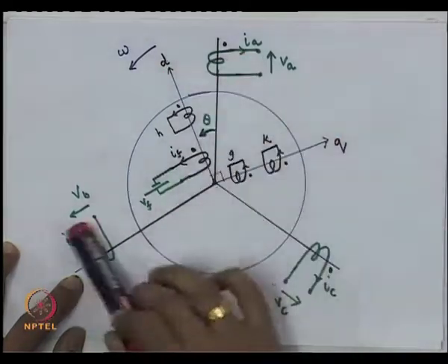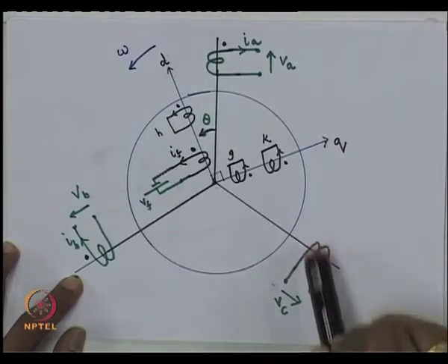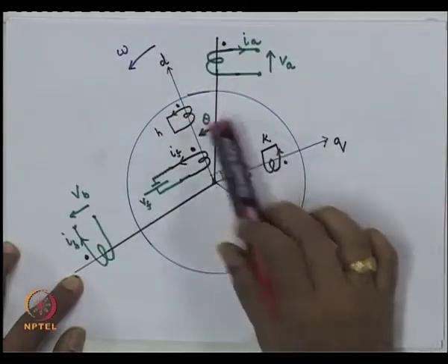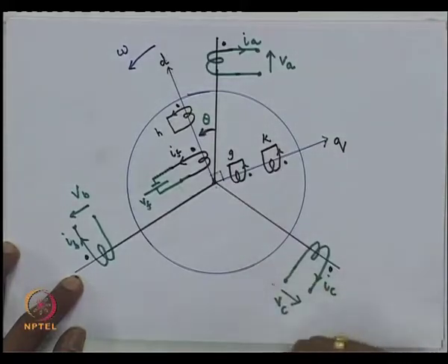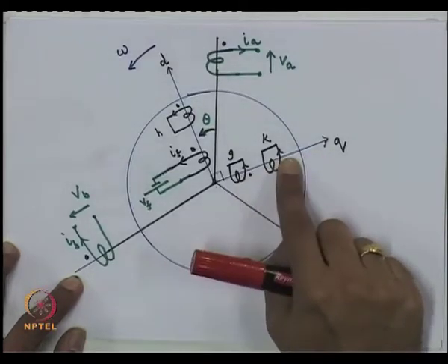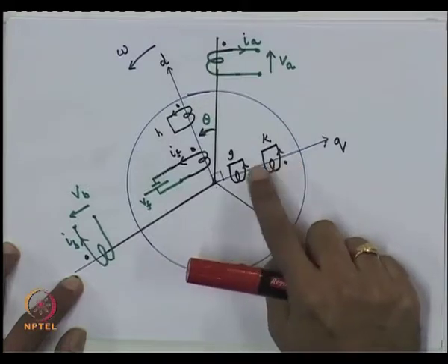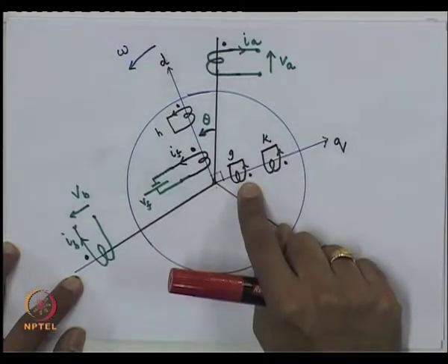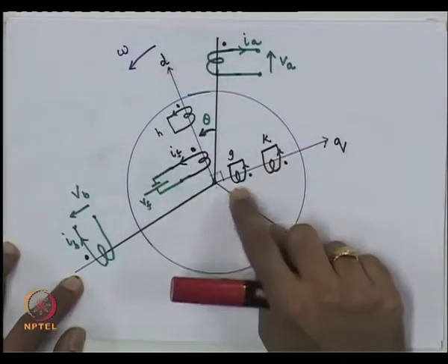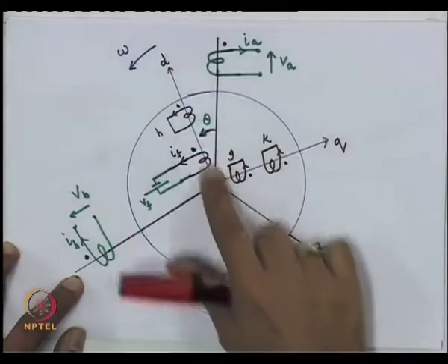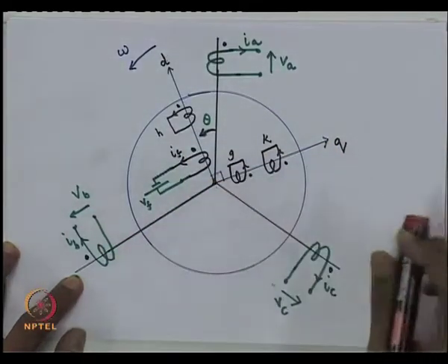So, what we do is model 3 windings for the phase windings which are on the stator, and you have a field winding, and these 3 other windings are cumulatively representing the damper winding and eddy current effects. Now, you may ask why 2, why not 3, or why 2, why not 1? The answer to this question is that this is a model and we will try to fit our observations into the model. So, we will assume that there are 2 windings on the quadrature axis and 2 windings on the direct axis, which completely capture the effects of the rotor circuits.